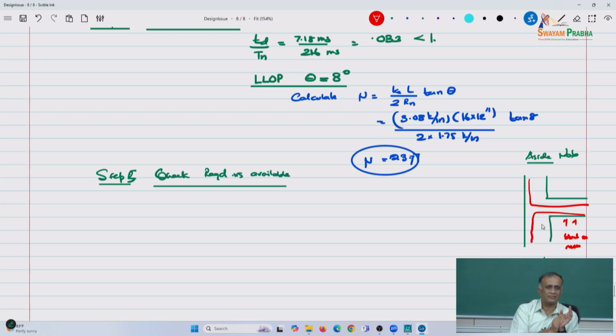Other things that are done: have you heard of strut and tie methods? Some of you in concrete would have heard of strut and tie. Strut and tie methods are very frequently used in the design of connections. In connections, you will calculate your dynamic reactions. It's a good method to use in blast design. And how would you reinforce in a strut and tie method?